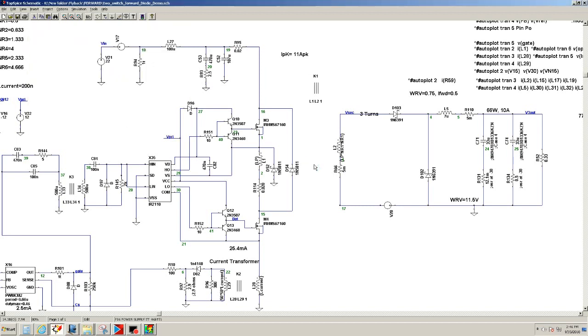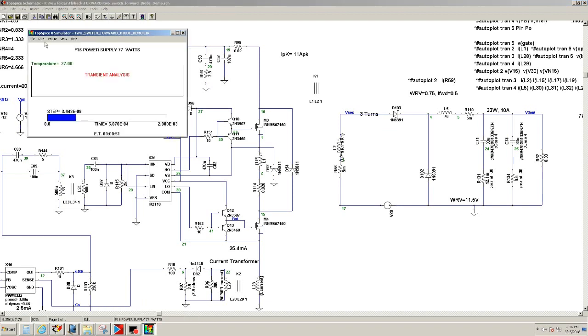And I'd like to add or talk about these. Right now what I'm doing is I'm running approximately 33 watts, 10 amps, and this should be a 3.3 volt driver or converter, a forward converter. I'm using the 1N6391. So I'm going to take a look at that just a little bit. Just take a real quick look.